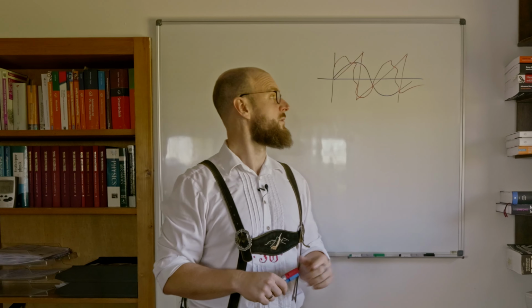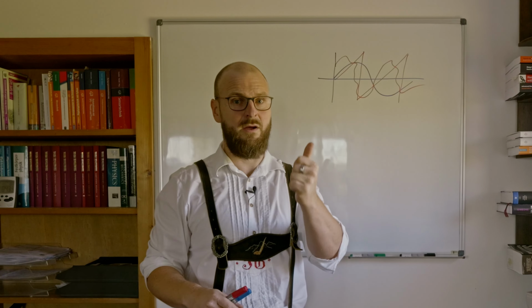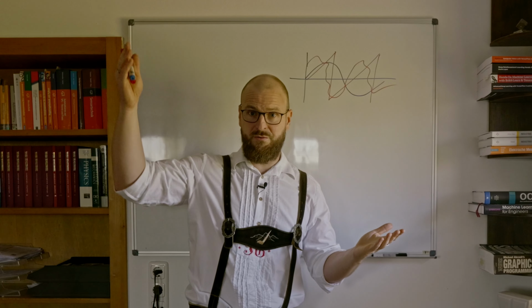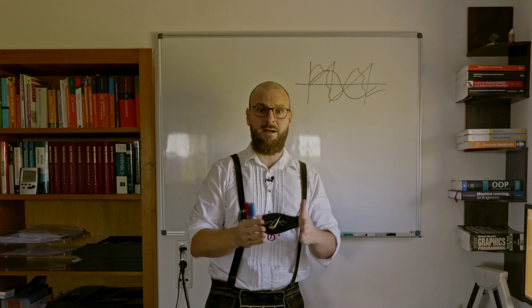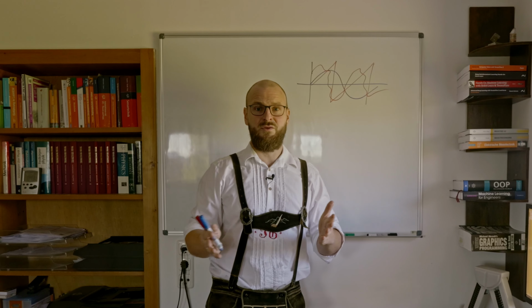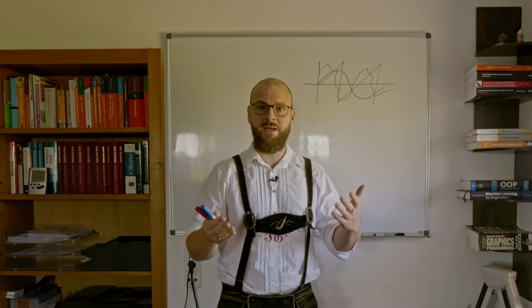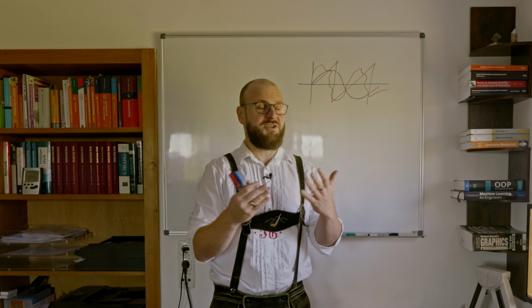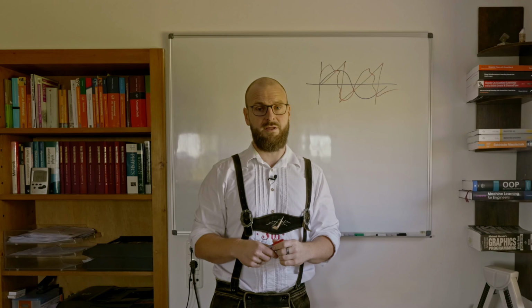That means looking only at one sine or one cosine function, or one exponential function with an imaginary exponent, is enough, because summing them up won't change the way to solve those linear differential equations, and by that won't change anything in the basic behavior of our alternating voltage or current.